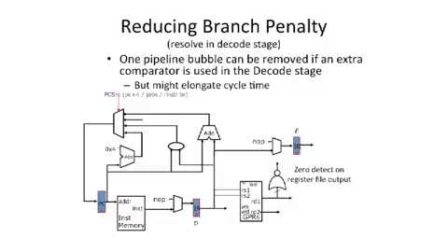So this is the 0 detector. One of the interesting things is this is actually a little bit easier than doing a full comparison with 0. Because to do a 0 detect, you can basically build an optimized OR tree and then take the negation of it. Sometimes people even do this with wire ORs or more analog-y circuits.